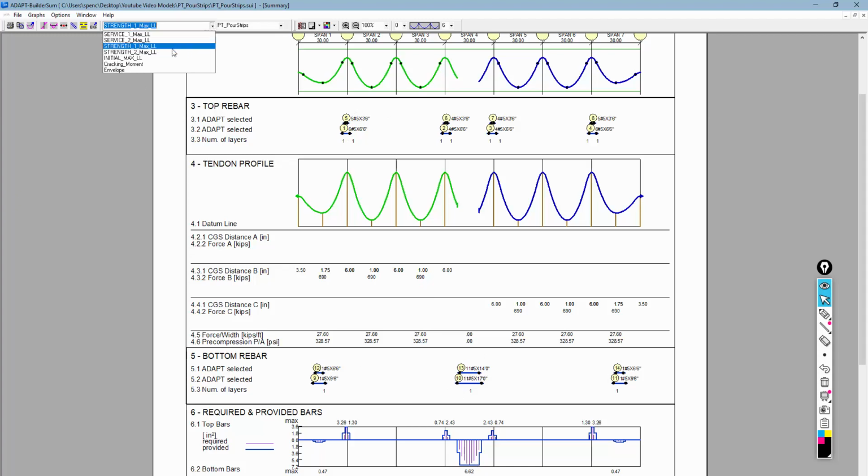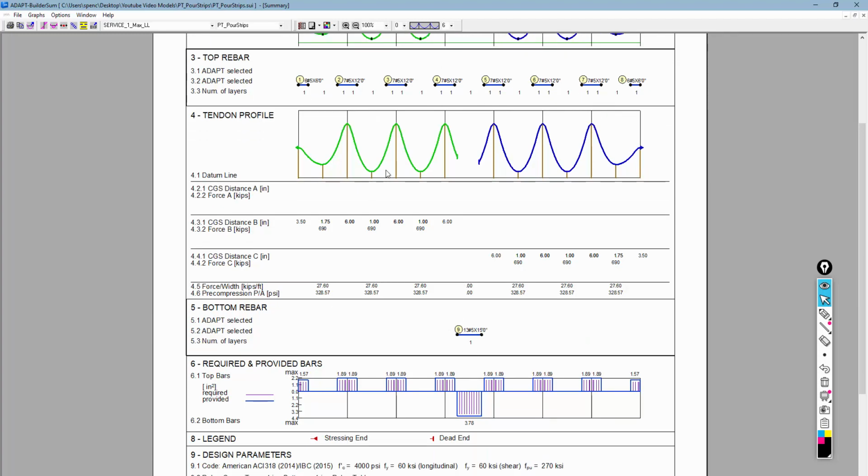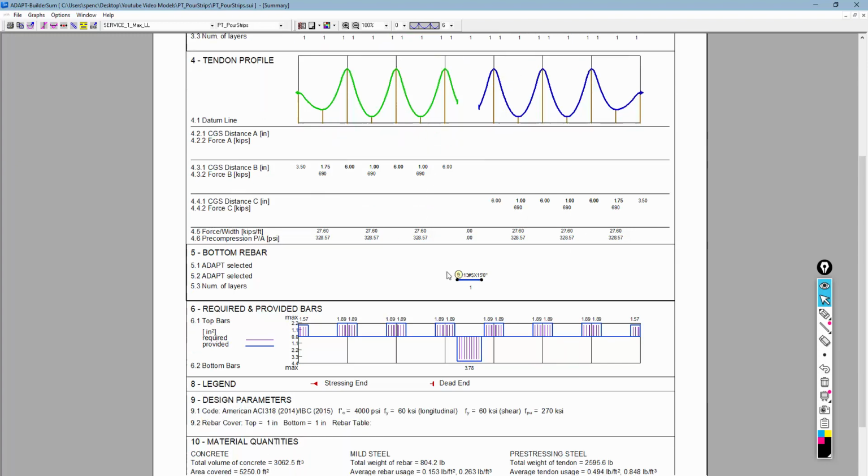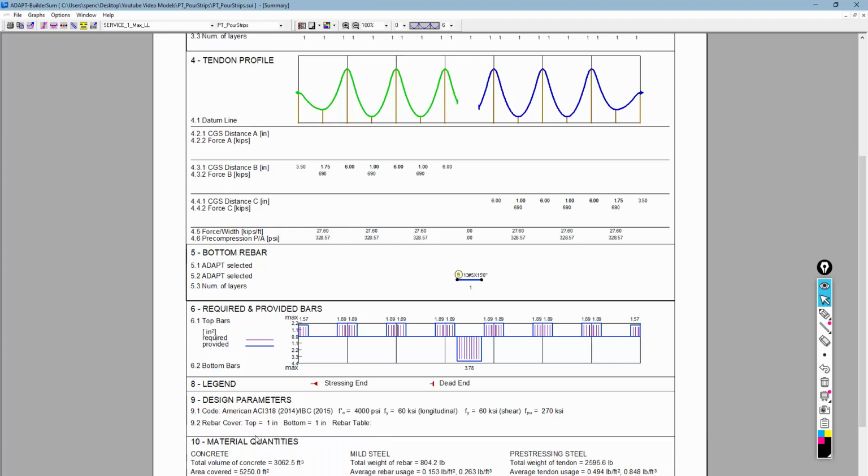And then for minimum reinforcement, you can see this is really based on post-tensioning two-way slab prescriptive reinforcement here at the bottom, because the stress level may be low enough in this particular condition. We don't need any reinforcement at the bottom in these other spans, except for here again, this is an RC span, so we need essentially minimum temperature steel, shrinkage steel for this location. And this should equal, for example, 0.0018 times area gross for ACI code. This is being designed at ACI 318.